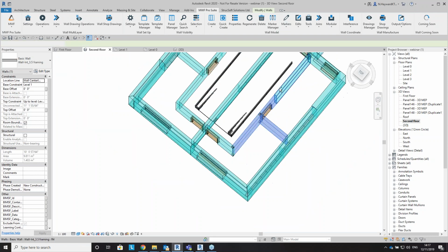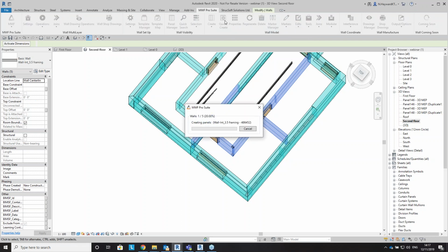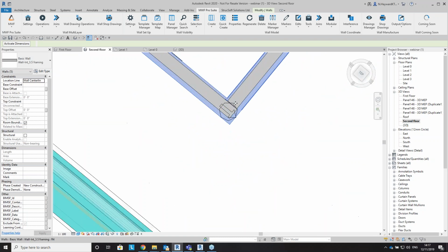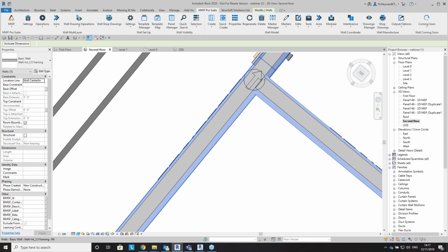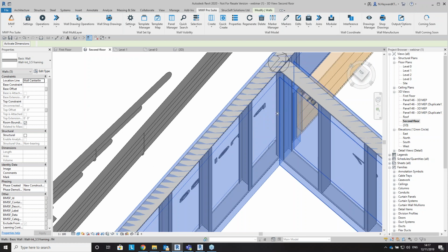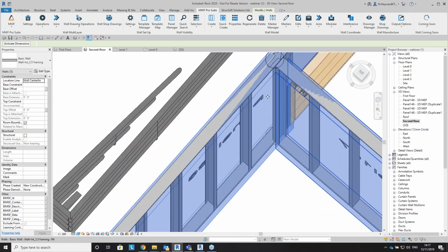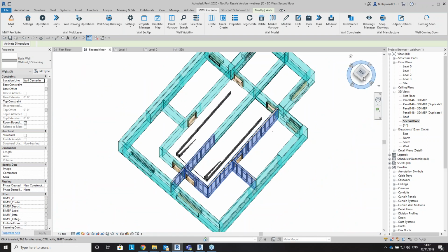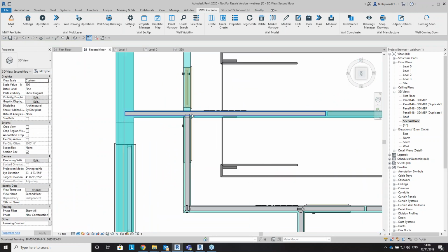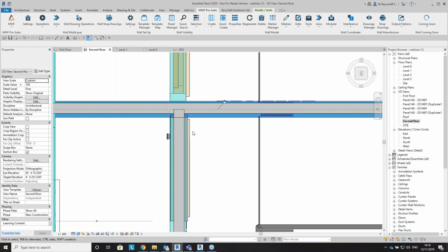And I'm just going to quickly create these walls. Just take a couple of seconds. And here we go. So basically the join is set up sort of like a rule set to tell the panel where to stop. It's placed like an extra member in here, just so everything joins cohesively. I mean, you wouldn't even realize that it's done anything, but if I was just to place a join into this set of walls here,